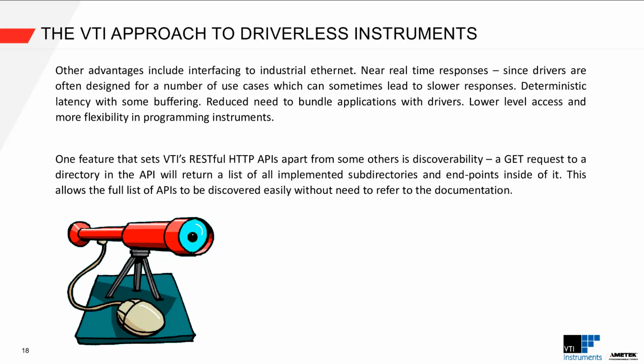So if you get hardware and you get the proprietary driver or the LXI IVI driver that belongs with that, quite often that driver will support multiple types of hardware. And so it can lead to slower responses because you have to drill through the driver to get to the data that you want. And so by directly accessing the instrument using REST, you reduce a lot of that response time.